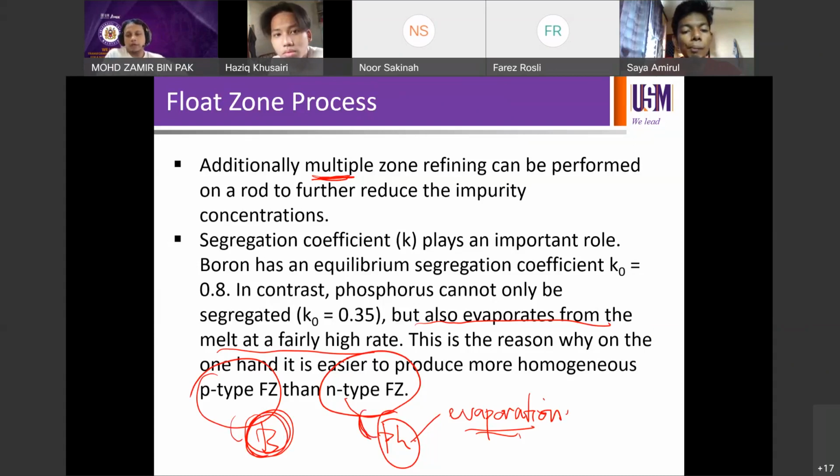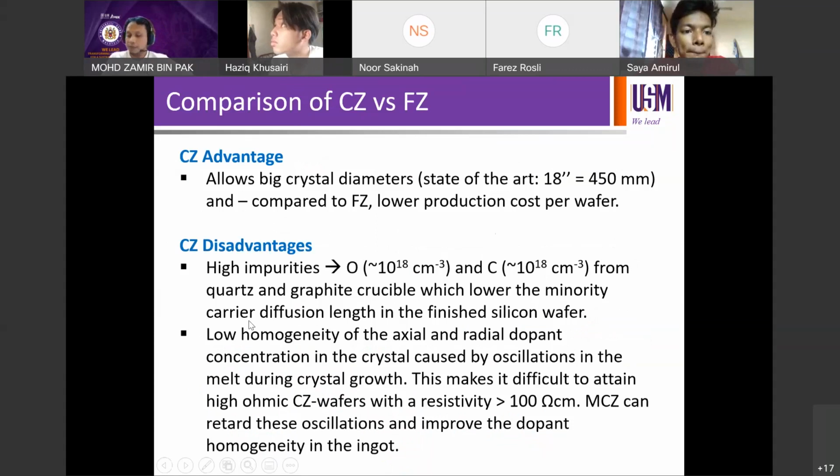That's why we discussed in our previous class the doping uniformity along the ingot for n-type wafers, where you cannot use most of the ingots that you have grown in the Czochralski process. You will have an issue with n-type because you need to chop off more regions to be remelted for another growth process due to the non-uniformity issue. But this is not happening in p-type because it is based on boron.